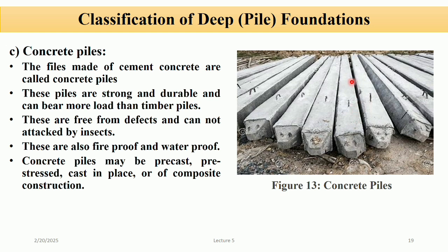Concrete piles. The piles which are made of reinforced concrete are known as concrete piles. They are strong and durable and can bear more load than timber piles. They are free from defects and cannot be attacked by insects, and they are fireproof and waterproof as well. The advantages of concrete piles are that they can support heavy structures like bridges and skyscrapers, they are durable and strong, do not rust like steel piles, and are economical for large projects.